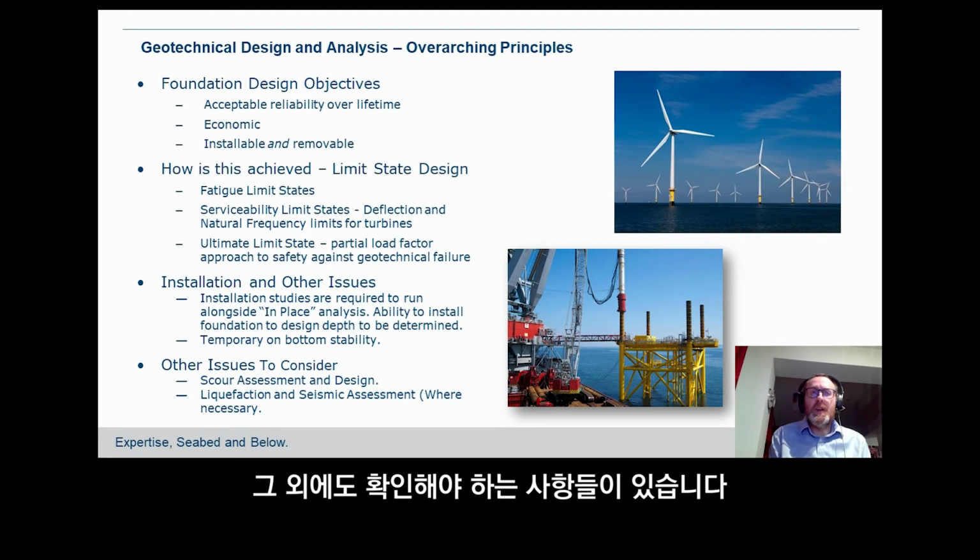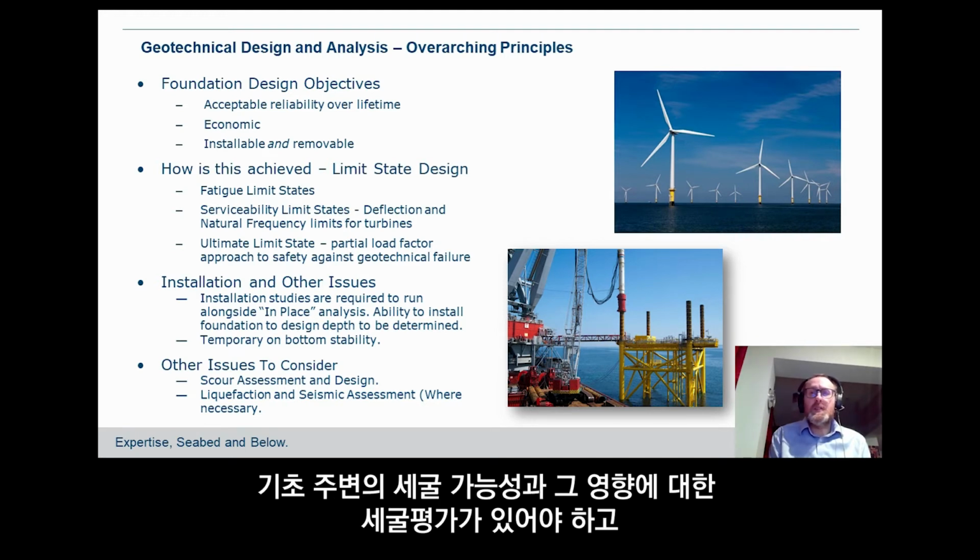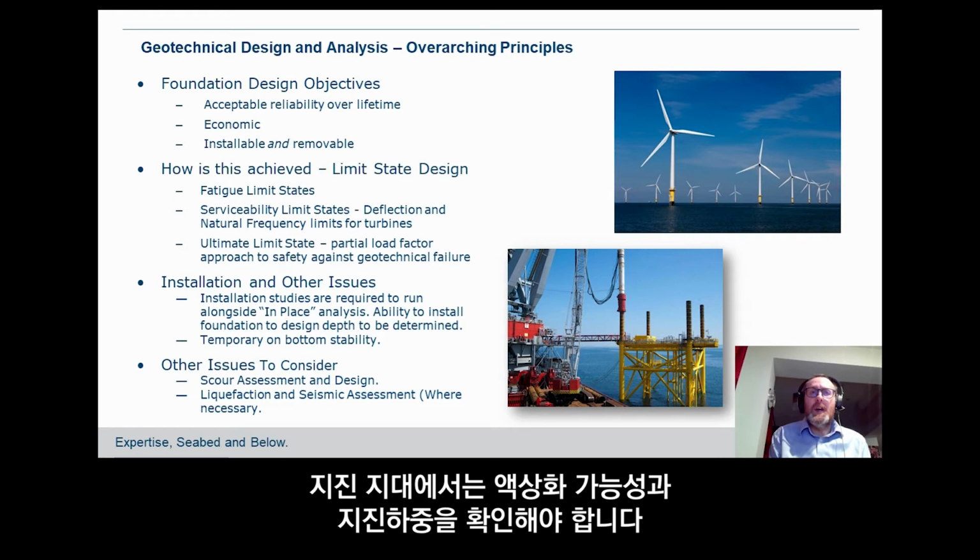In addition to that, there are specific other issues that we have to look at. Scour assessment, scouring around foundations and the possible impact that might have needs to be looked at. And also in seismic areas, liquefaction or seismic loading also have to be looked at.